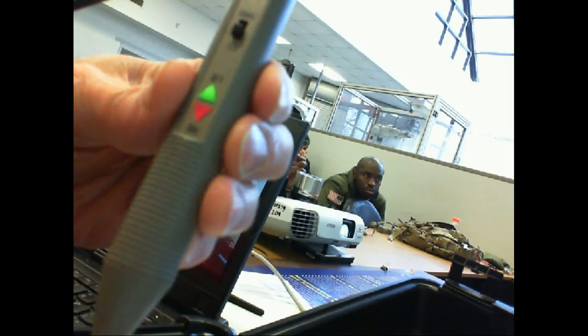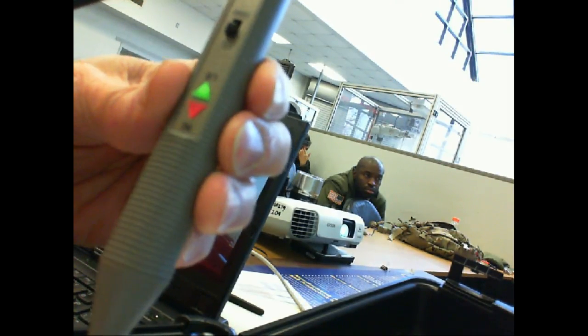So anytime you see that, it means it's doing this. So it can't be high. It can't have plus 5 volts and 0 at the same time. You understand that? So when you see both of them come on, what does that mean? It means you're seeing something pulse, right? If the red is brighter than the green, it means it's high more than it's low. If the green is brighter than the red, it means it's low more than it's high.